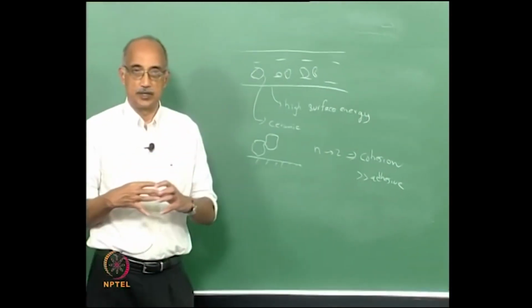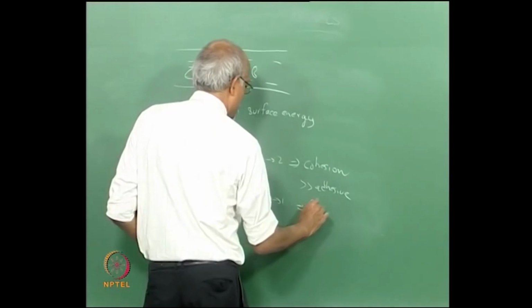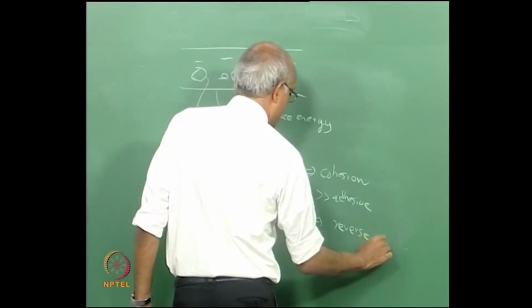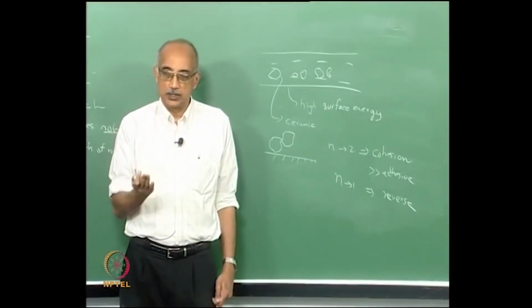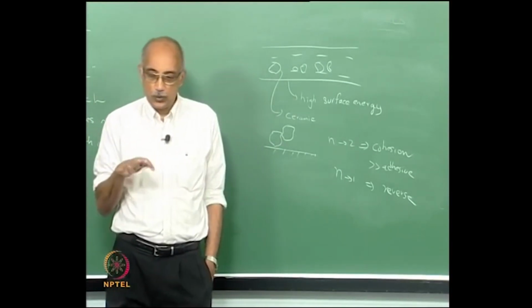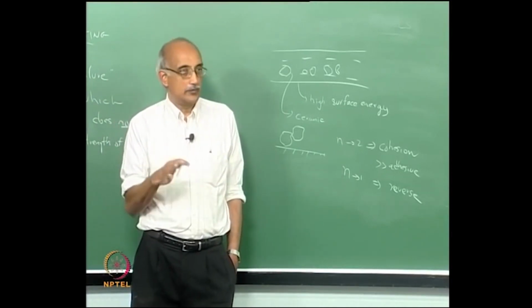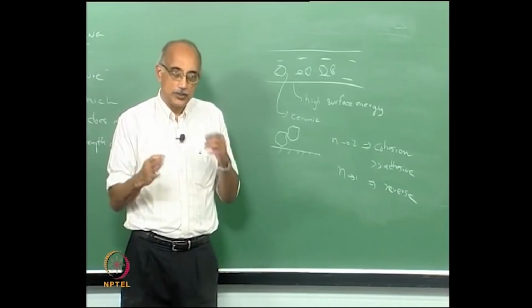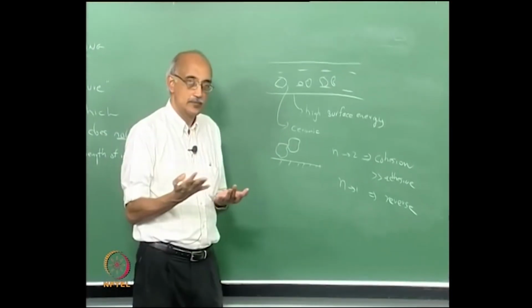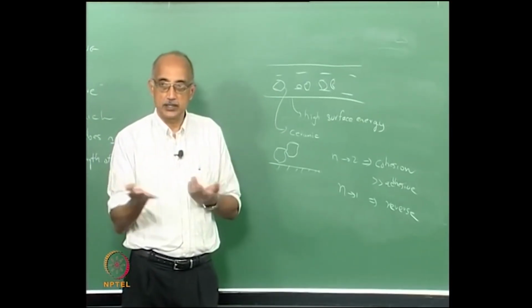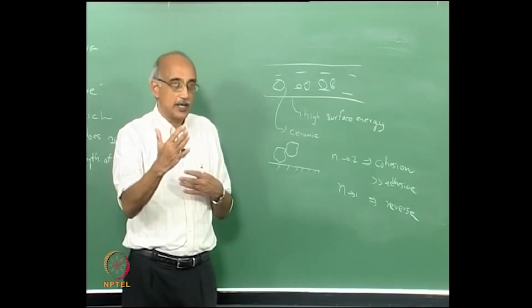So, the particle cluster will essentially stay intact, whereas as n tends to 1, the reverse will happen, and there will be a greater tendency for particles to attach themselves to the surface. And that is why, when I asked earlier whether flow is preferably cohesive or non-cohesive, the answer that non-cohesive is better does not always apply, because in a non-cohesive flow it is also very easy to lose material because particles can accidentally attach themselves to surfaces that they are flowing past, and there can be substantial loss of material. Whereas in cohesive flow, the probability of that happening is very low.